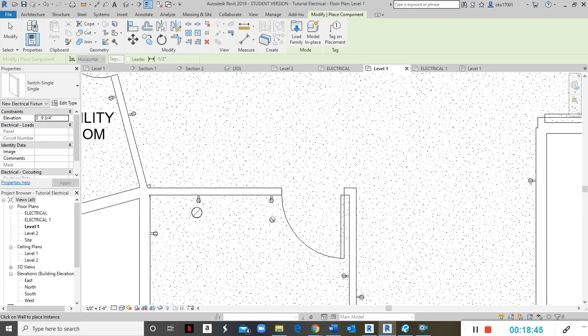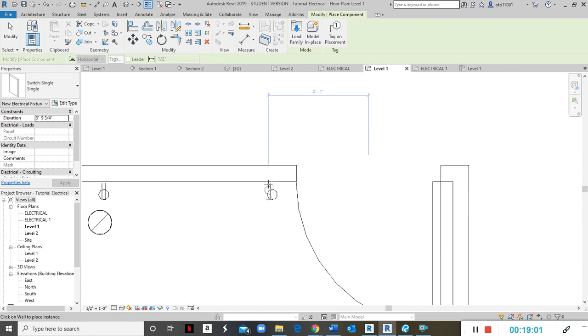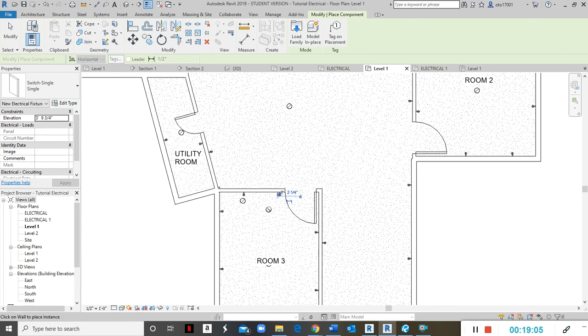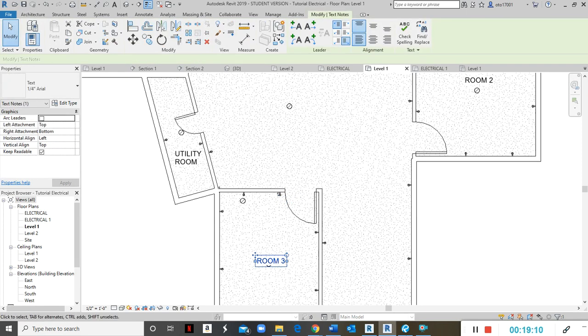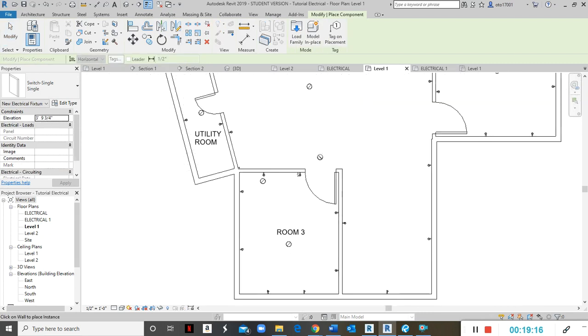So I want to have a switch in here. When I open the door, first of all, this outside is going to be below. It's not going to be on top. I don't want to put it on top so that it doesn't look bad. So I'll just put it right here, about, let's say, right over here. Yeah, next to it. That's to control these lights in here. Let me move this room tag up above so you can see the lights. There we go. Yeah, so you can click on this, type CS, create similar.